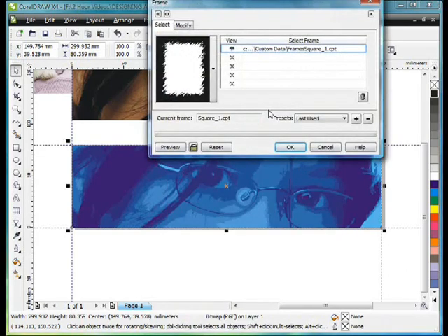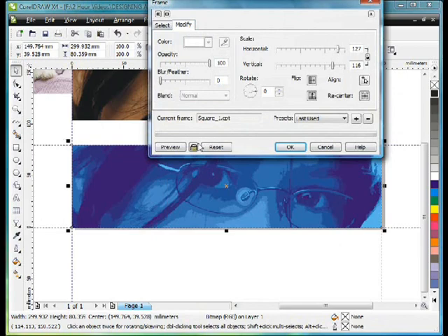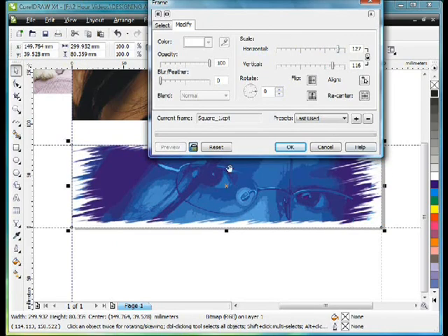One of my favorite effects. What this frame does is it'll actually cut in all the way around the edge of my image. And these sliders, horizontal and vertical, can adjust how much it cuts into your image, left and right, top and bottom. These cut-in areas are transparent. In other words, we'll be able to see a color through. If we had not turned on transparent bitmap, we wouldn't be able to do this.